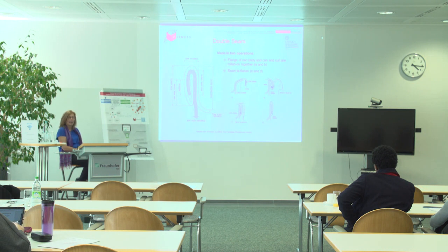So in a can industry, all these details are measured and controlled as a normal routine of quality control. So if you work in any food plant that uses metal cans, you have people going to the lines, collecting cans and checking for this whole set of parameters that compose the double seam.